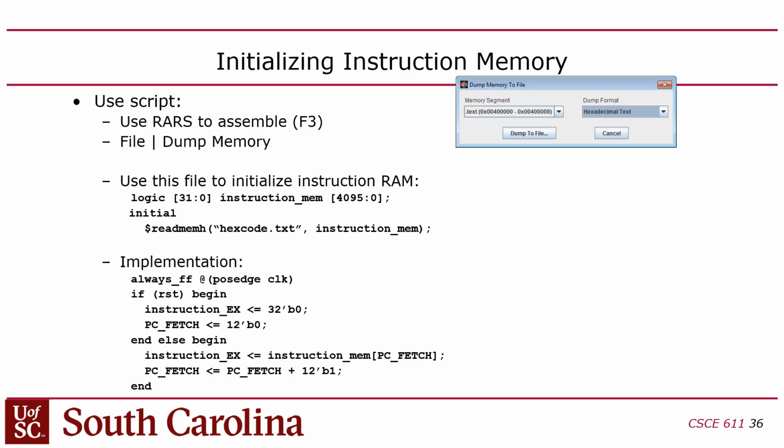Are we going to be doing a demo for that? Yes, there's a demo for Lab 3. We're going to ask you to put in the value 31, and you're going to flip the switches, and then we should see 31 on there, right? So you're going to put a binary 31 on the switches, but it should show a decimal 31 on the hex displays is the objective. But this time we get to have all the hex displays, I think, 30? Because if you put all the switches up, it's 262,000. Oh, no, sorry, that's still 6 digits, never mind. But the next lab will be able to use all the hex displays. Digits, rather.